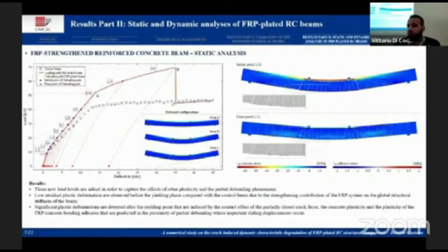After the validation procedures, an FRP strengthened reinforced concrete beam has been analyzed with the same methodologies and procedures used on the control beam. We added 3 new load levels in order to capture the rebar yielding and FRP debonding phenomena. We can note immediately that after the yielding phase, each curve exhibits low residual plastic deformation compared to the control beam, due to the strengthening effect provided by the FRP that influenced the global stiffening of the beam. Instead, after the yielding phase, due to nonlinear phenomena such as concrete plasticity and partial contact, we have big residual plastic deformation.